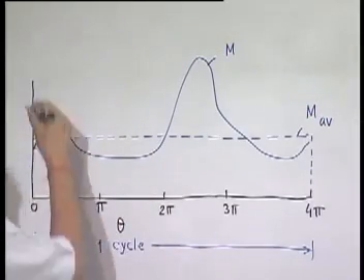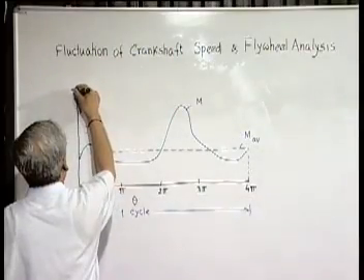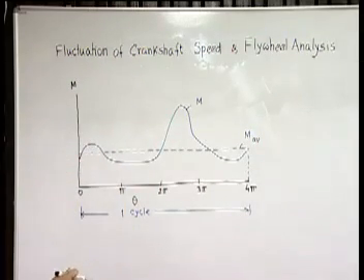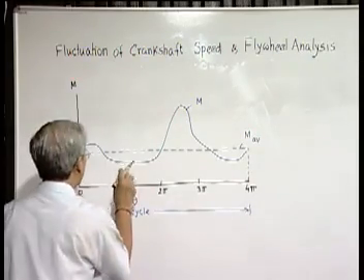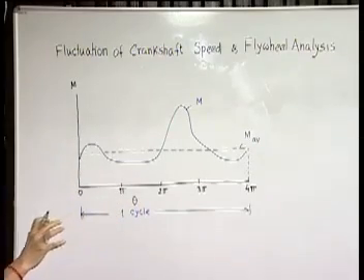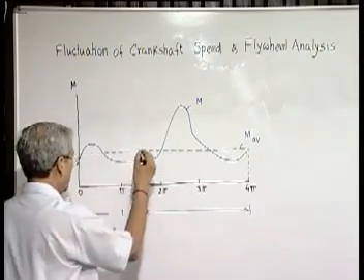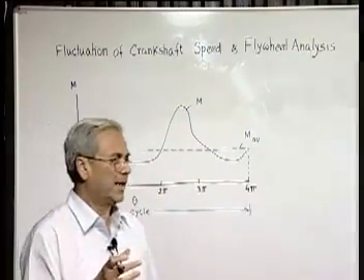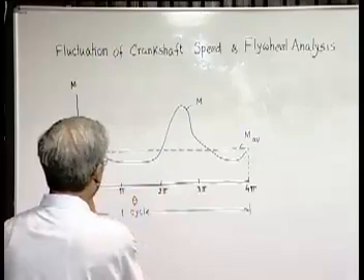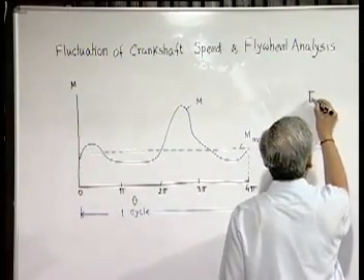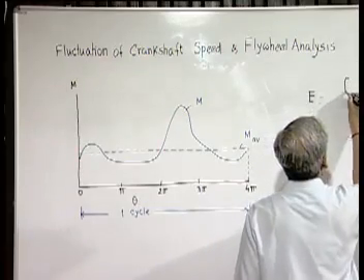Now, the total work done by the engine in one cycle is what? Because if the crankshaft is rotated by an infinitesimal angle d theta when the turning moment on it is m, then the work done by the engine is m d theta. So therefore, in the whole cycle, the total amount of energy which is generated can be written as